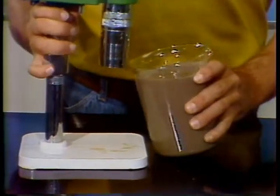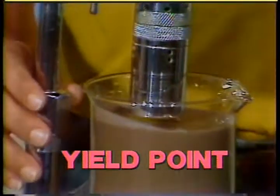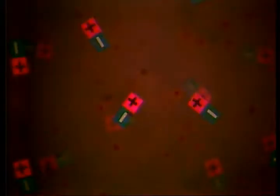There's also a factor called yield point. This is the fluid's resistance to flow as a result of electrical attraction. Many muds have a feature that aids in maintaining viscosity by particles pulling together like microscopic magnets. They try to join together as they come near one another. It's not just a resistance caused by friction of particles. It's resistance caused by the electrical attraction of the mud particles to one another.